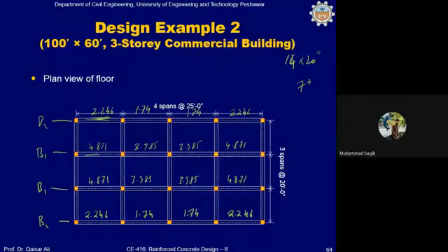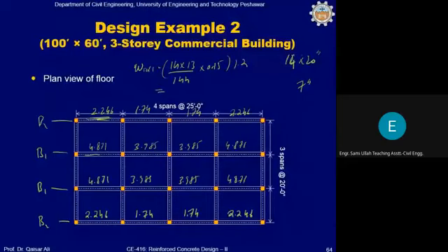13 inch. So the cross sectional area of the web, this is the self weight of the web, is equal to 14 by 13 divided by 144 multiplied by 0.15 and multiplied by 1.2. This is the self weight of the web. You have to add this value to all these values.